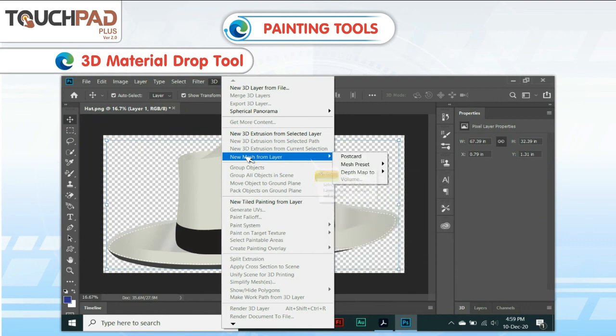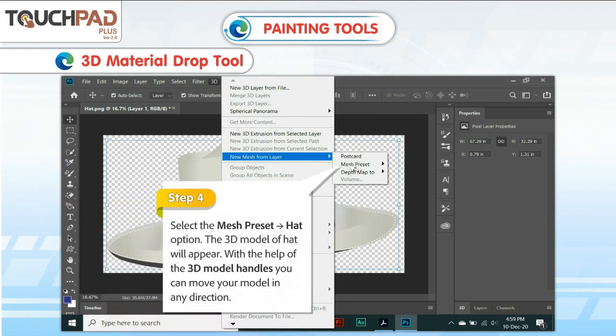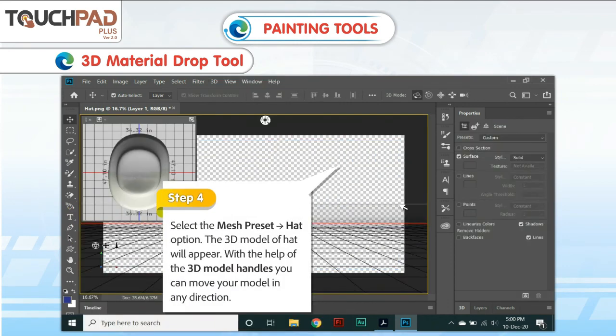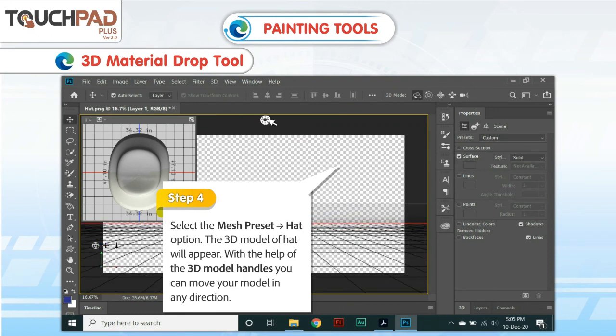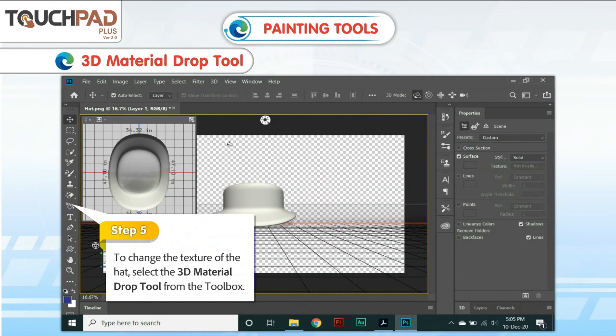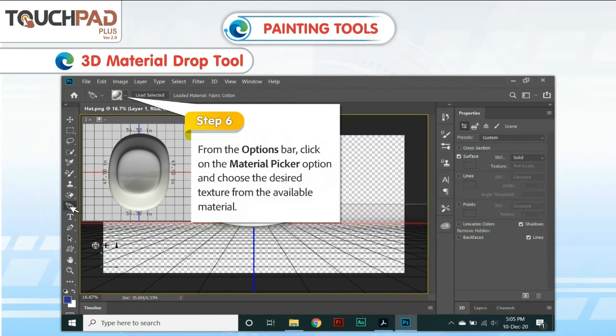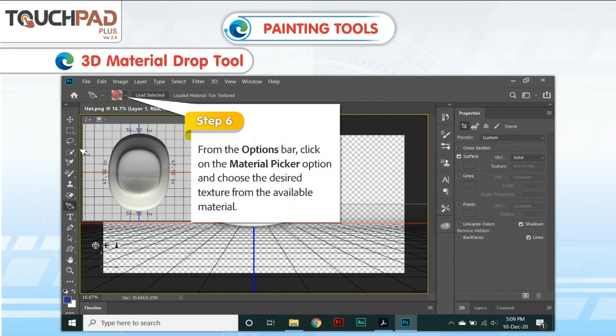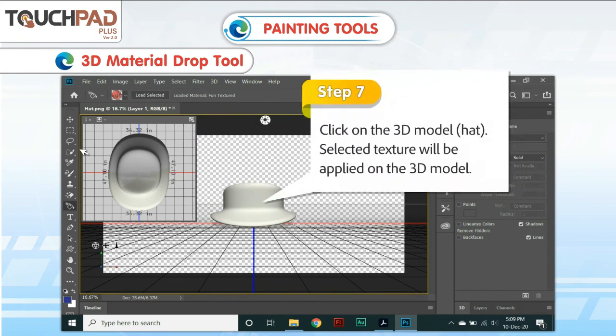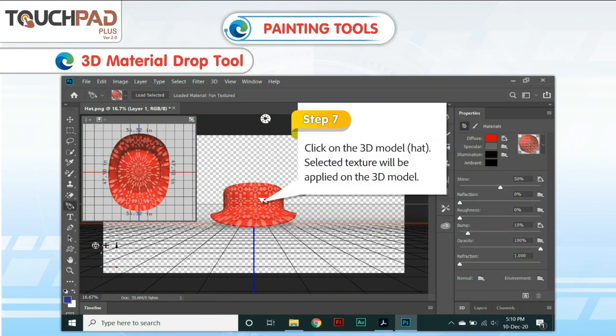A sub-menu will appear. Step 4. Select the Mesh preset. Go to the Hat option. The 3D model of a hat will appear. With the help of the 3D model handles, you can move your model in any direction. Step 5. To change the texture of the hat, select the 3D Material Drop tool from the toolbox. Step 6. From the options bar, click on the Material Picker option and choose the desired texture from the available materials. Step 7. Click on the 3D model, the hat. The selected texture will be applied on the 3D model.